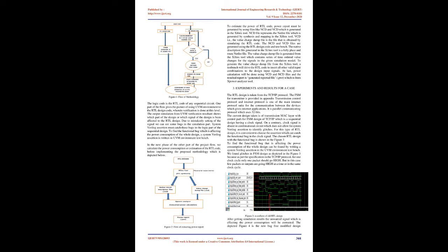The NCD file represents the netlist file, which is generated by synthesis and mapping in the Xilinx tool. The VCD file, the value change dump file, is the file that is obtained by simulating the RTL code. The NCD and VCD files are generated using the RTL design code and test bench. The native circuit description file generated in the Xilinx tool is a fully placed and routed netlist file.